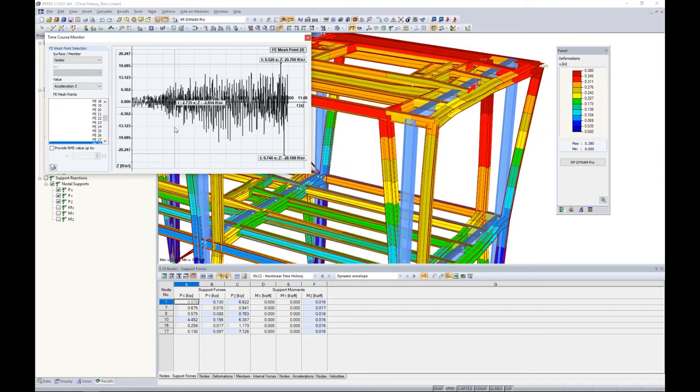So for today, this is an industrial structure. We probably won't have too many humans occupying the structure, but if you're designing a hotel or an office where people are sitting or sleeping or whatever else all day long, accelerations that are extremely high can be very unpleasant, intolerable, and it's something that a lot of codes really place limitations on, and they set this usually at less than 10% of G.